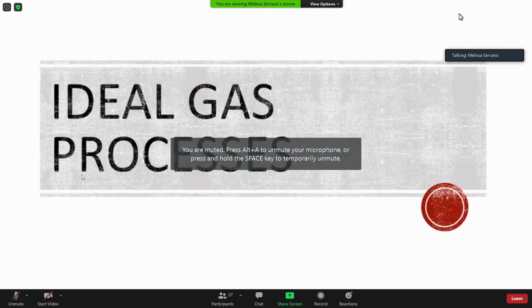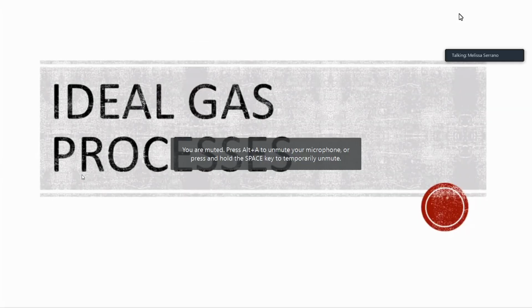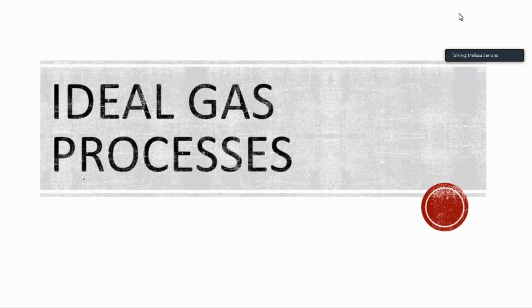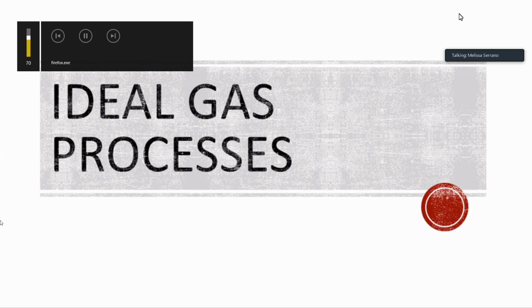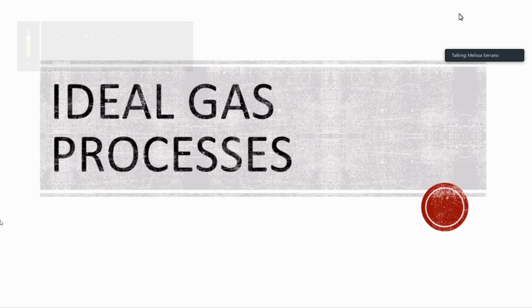Unlike a reversible process, what are the factors that affect our process, like friction, expansion or throttling, heat transfer through a finite temperature difference, or mixing of two different substances? Okay, so if we have those, we cannot just neglect them. They have an effect on the path, on the process, on the system, in such a way that we can no longer say that it is reversible. So it will be considered as an irreversible process.